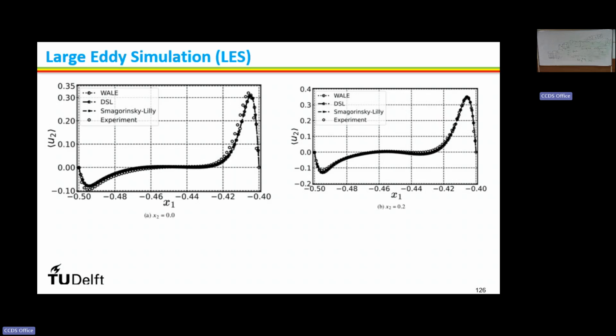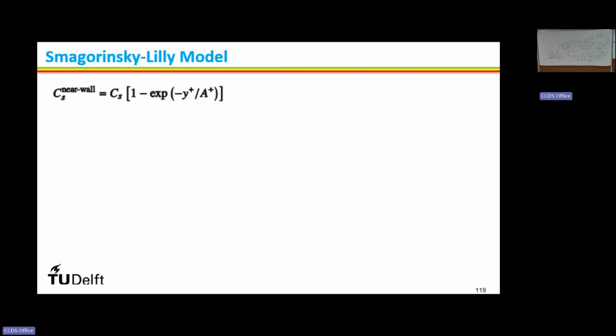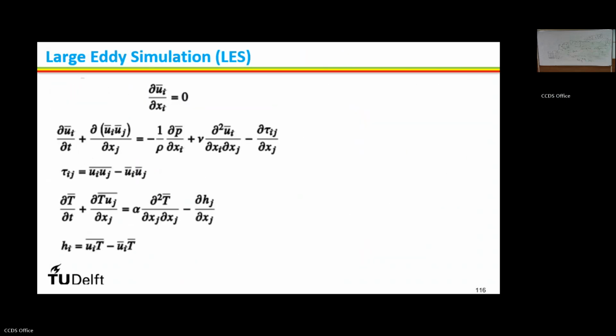So again, the problem with LES is getting converged statistics, right? What converged result? You will get the Reynolds stress, the turbulence stress. These are average quantities, right? What will happen during the run time?